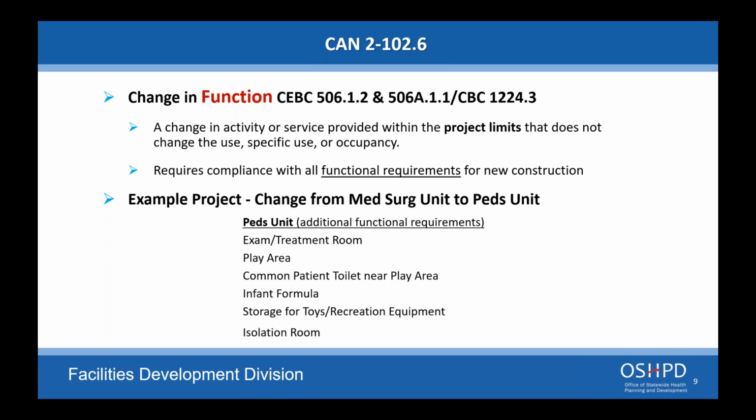This has been a request that we must update the corridor as well as the patient room so that the fire rating is corrected, i.e. if the existing room is 75 CFM positive, but there is no requirement on a rated corridor, do we need to make the room neutral as well as change the offset on the corridor so that it doesn't change the overall hospital?